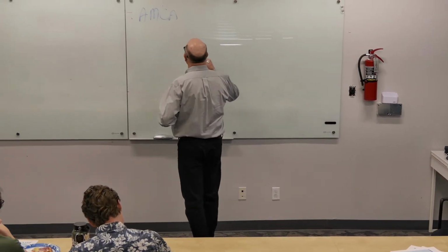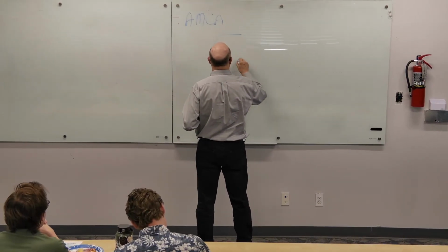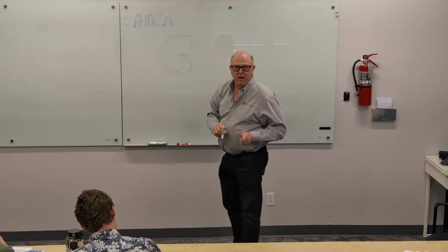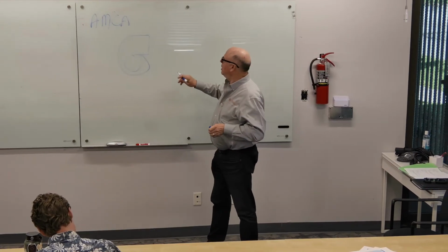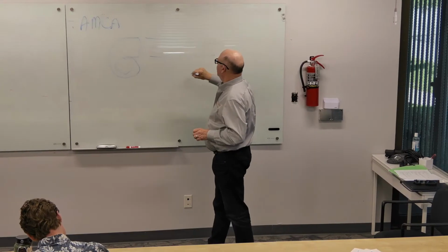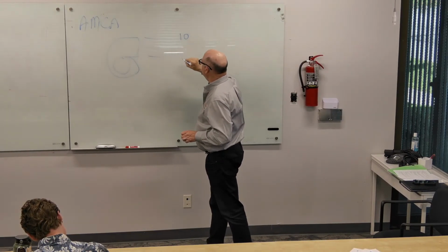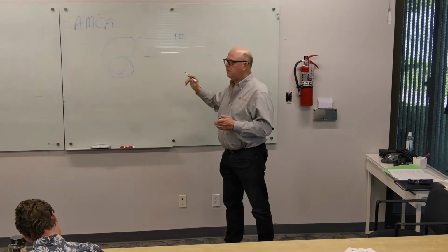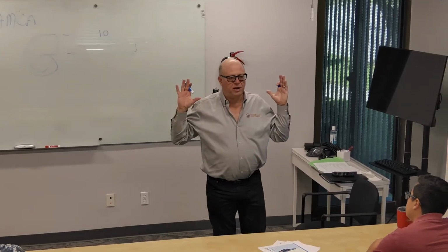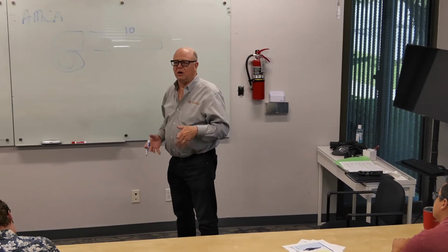The typical fan, we talked about a fan scroll, we talked about a fan wheel, right? The typical fan is rated with 10 duct diameters of straight distance, and then they put the little air probes down there after 10 diameters. And they construct the fan curve from this. So, the old school way, the way I learned, you start with the fan curve.